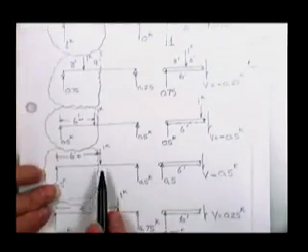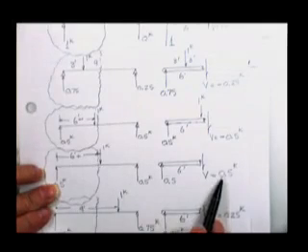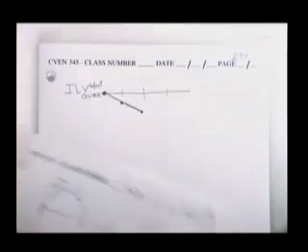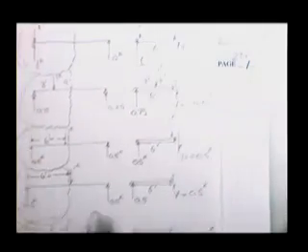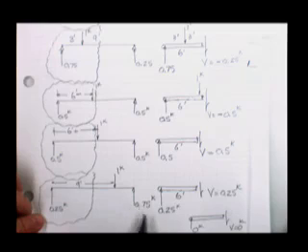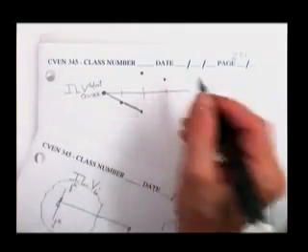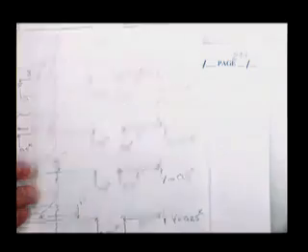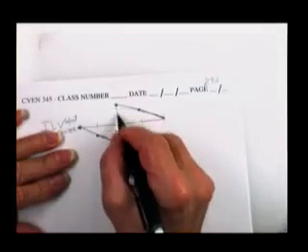When the load is moved slightly to the right of the point we're looking for the influence line, it turned to a plus 0.5. When it moved to the 9-foot mark, it got to be 0.25. And when it went to the end, it got to be 0. There's your influence line for shear at the middle.